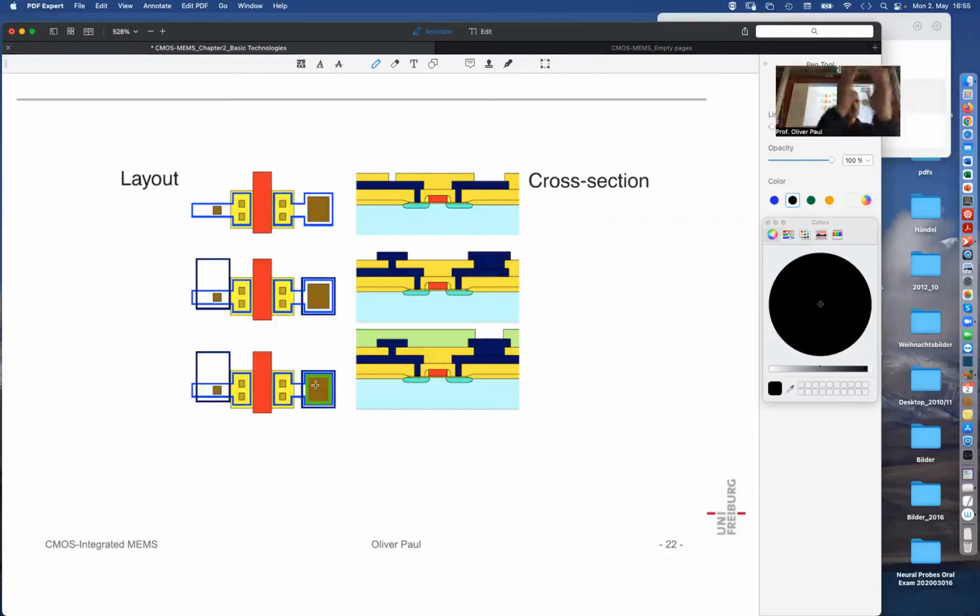And those 2D structures need to be superposed and need to be mentally translated into a physical reality that is 3D, that has cross sections, as I showed you before. Well, that's the challenge of designing, to have this view of how to realize a 2D cross-section as part of a 3D structure by masks that are essentially 2D from top.